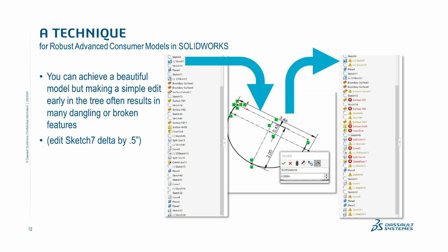What really identifies the problem is that surface modeling requires many features. And once you have many features that are dependent on one another in the tree, you're increasing, sometimes exponentially, the amount of potential failure because so many things are built on so many things. It's like a house of cards. You have a lot of dependency on one another, so the chances of failure are increased.